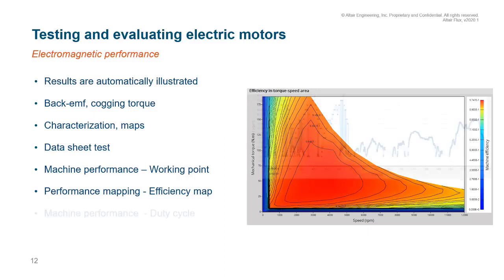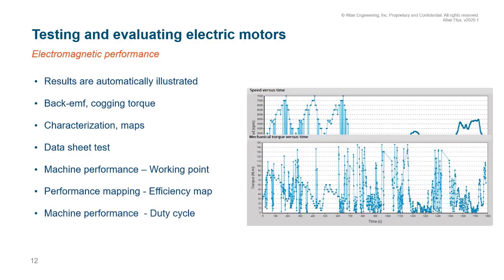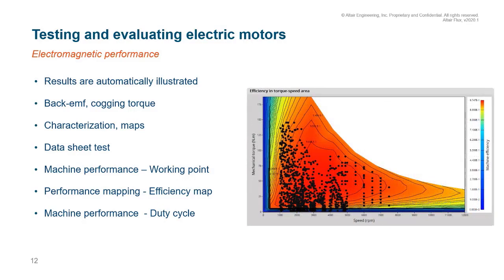On top of that, we can also evaluate a duty cycle defined by speed and torque against time and look at things like what are the average losses during the duty cycle and what is the average efficiency.